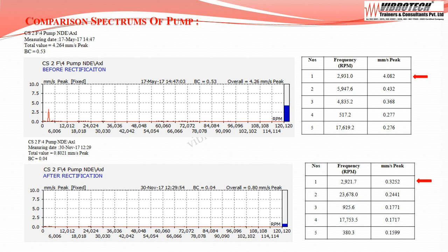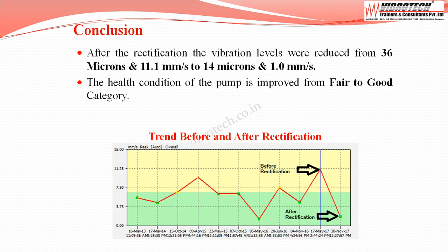After the rectification, the vibration levels were reduced from 36 microns and 11.1 mm per second to 14 microns and 1.0 mm per second. The health condition of the pump is improved from fair to good category.